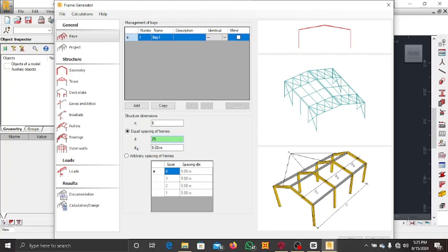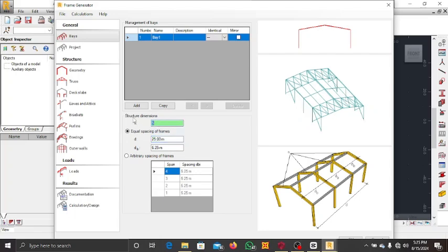Okay, for D, Structure dimensions, n is the number of roof rafters you want for that dimension. So we want about 5 spacing, so n is going to be 6. So you press enter, and once it's 6, you notice you can come here and count it: 1, 2, 3, 4, 5, 6. Okay, so the dB, the spacing between each of these 6 rafters, is 5